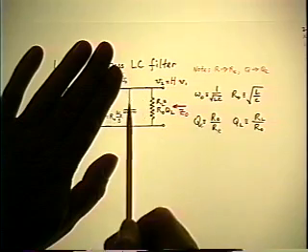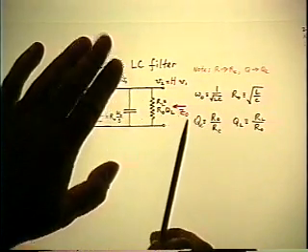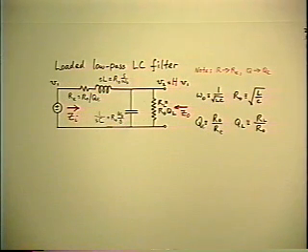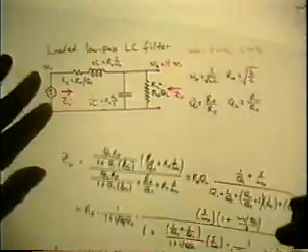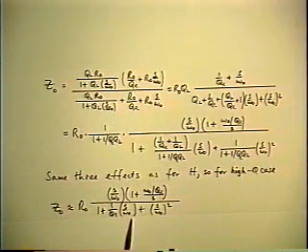So there is no change of output impedance, asymptote, slope towards infinite frequency, therefore no new normal pole or normal zero. Consistent with the result. Analytically, no additional poles or zeros of any kind caused by loading.